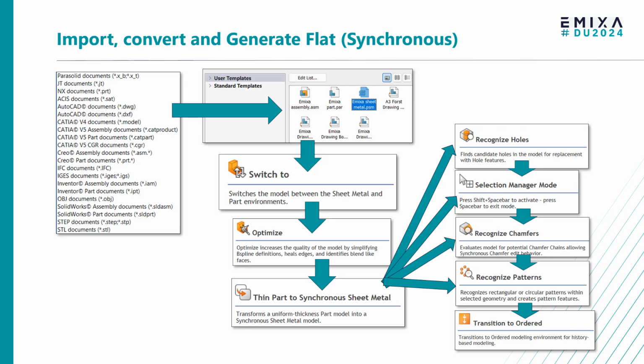Okay, here's one of my favourite bits now. Import, convert and generate flat in synchronous. So Solid Edge supports all the major CAD systems. If it won't come into Solid Edge, find a system that saves it out as a STEP file. Pretty much everything will do STEP file. If it doesn't, it will do IGES or some other kind of file format.